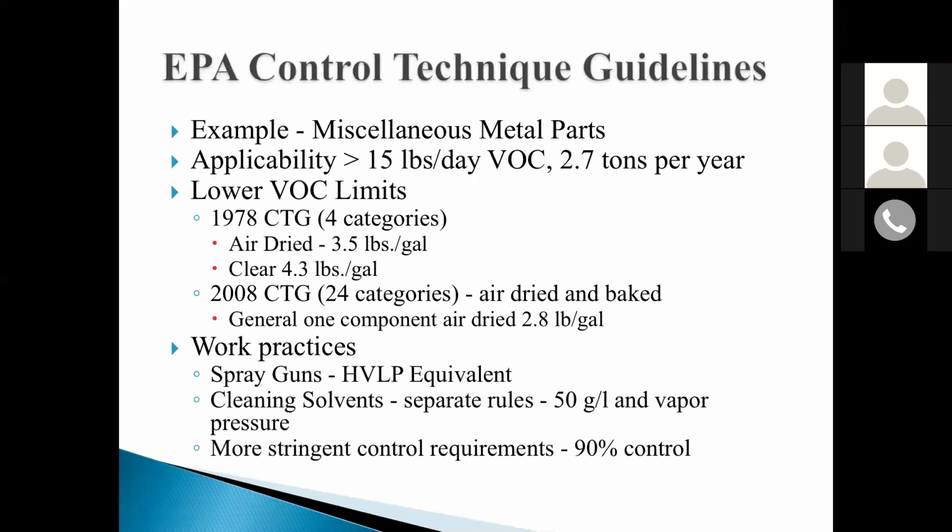So would that mean greater solids content, perhaps, or just less VOC? Correct. It could be greater solids. It could be exempt compounds. It could be waterborne technology. Any of the three. Could be really pushing out there. Powder coatings, for example. But there are other technologies. It's just a matter of reaching out to the coating manufacturers, working through it. There probably are going to be slight differences in how those products are applied, the type of equipment. Unfortunately, that's the problem with lowering these limits. Things change, and you just have to work through it to get the product you need and get the performance you're looking for.